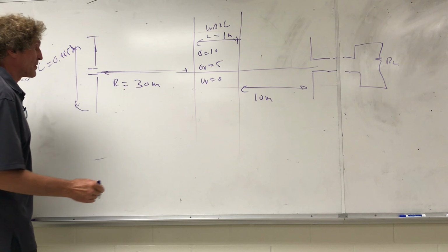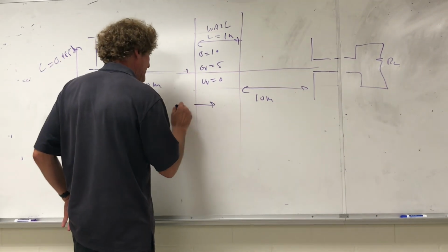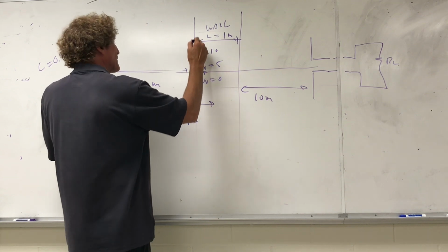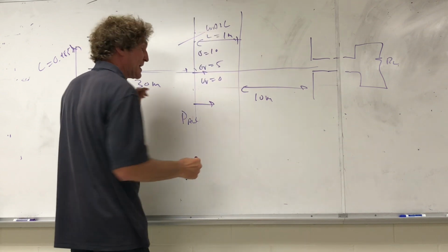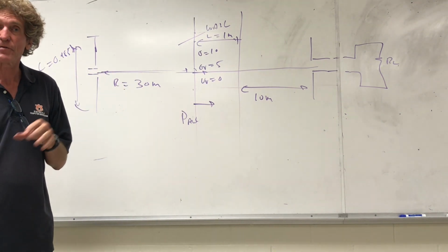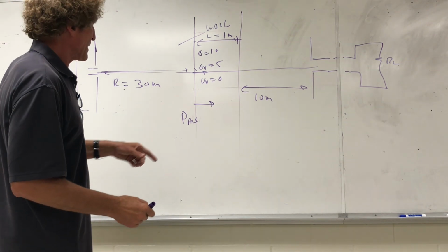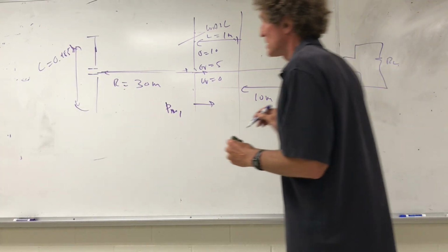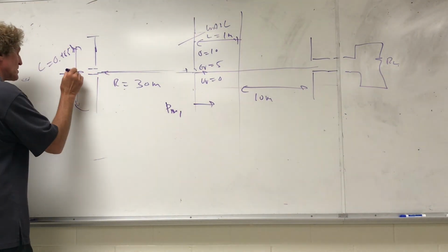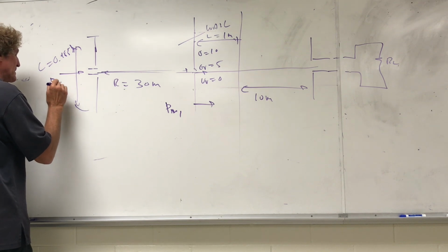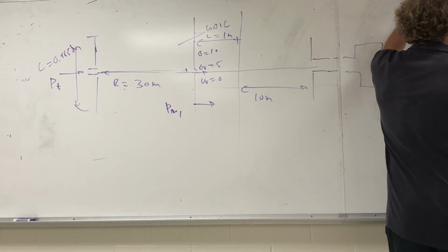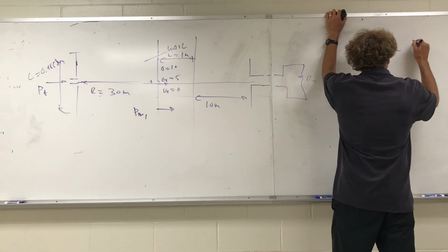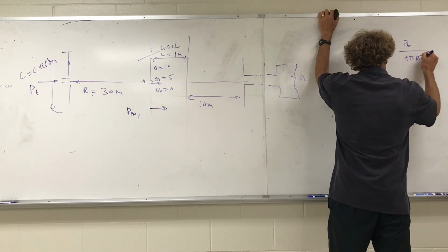If they're that way, what I need is the power density right here. I need P_AV, right at this point. We're going to move and start getting the power density at different heights, and it'll be at a different angle. That will be a reflection coefficient you have to enter in. So let's go ahead and do it. This instant power density, I'll call it P_AV1 right there. I'm assuming it's transmitting a certain amount of power, P_T. So I assume P_T, that means the average power density at the wall, P_AV1, would be equal to P_T over 4 pi R squared.